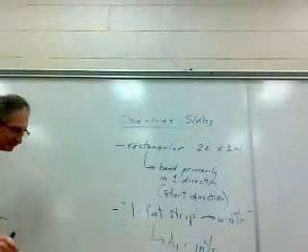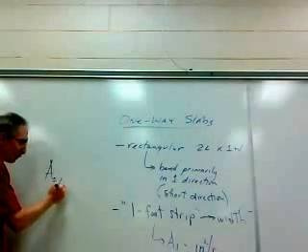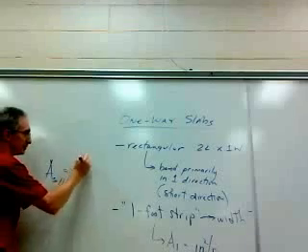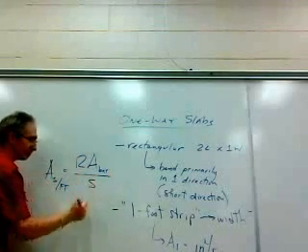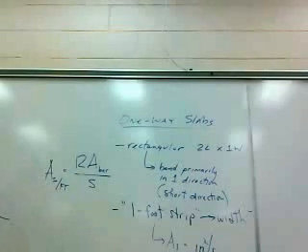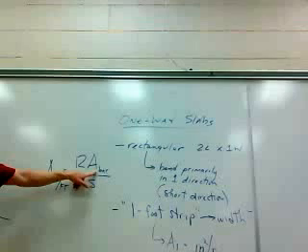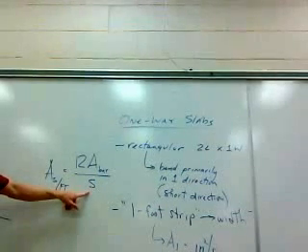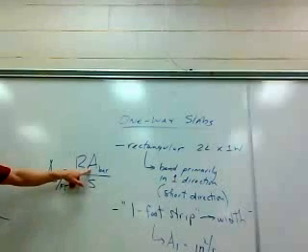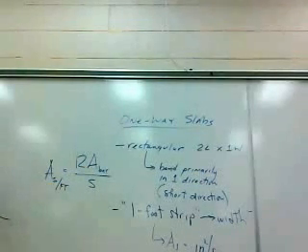The general formula, there's a couple of them, but for area of steel per foot, would be 12 times the area of the bar divided by the spacing of that bar. What's that? I thought that was an R. 12. Oh, wow, 12. Yeah, that's a 12.